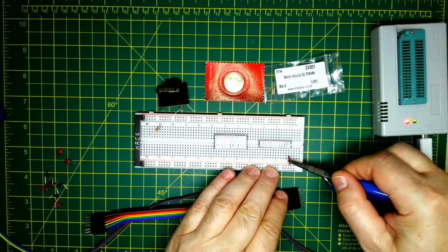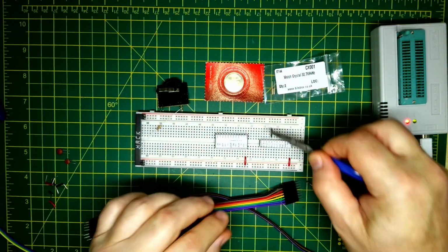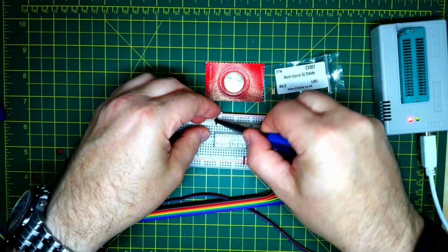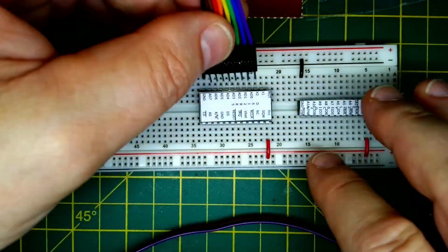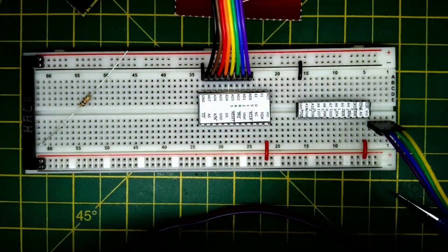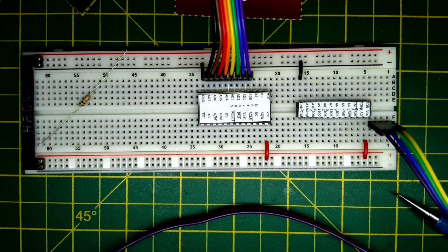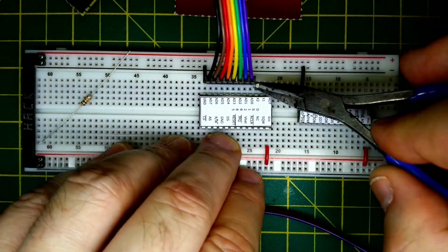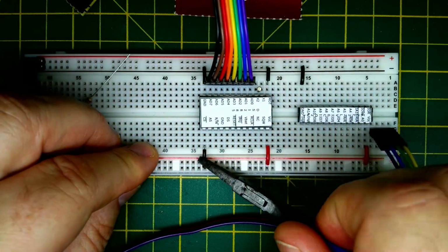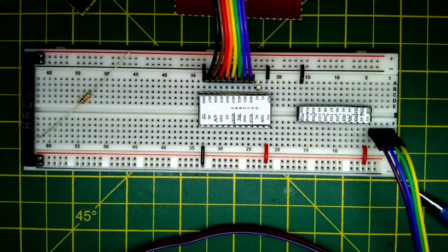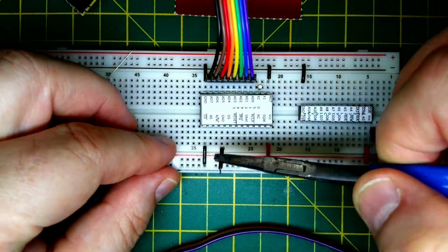So just press the chips in and connect up the power lines. Then this is the lower address line, A0 to A3, and the data bus coming in at the top there. Just put in the crystal, which is very small from a watch. And then the chip select and the Motorola Intel, set to Intel.